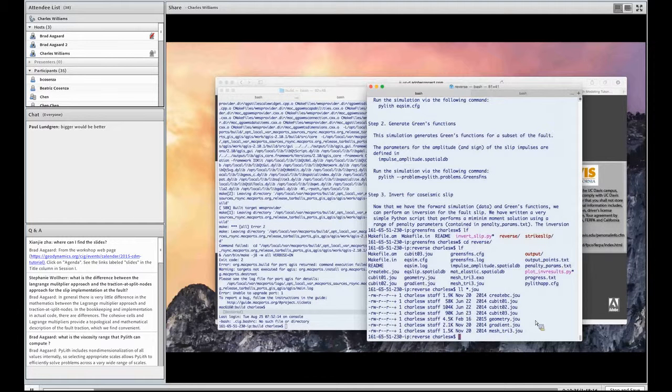We have a geometry file. We have a gradient file because we're producing a graded mesh that increases the mesh size as we move away from the part of the fault that we're interested in. We have another part, this create BC, that creates the boundary conditions that we want. And then finally, the one that calls all of these is this mesh_try3.journal file.